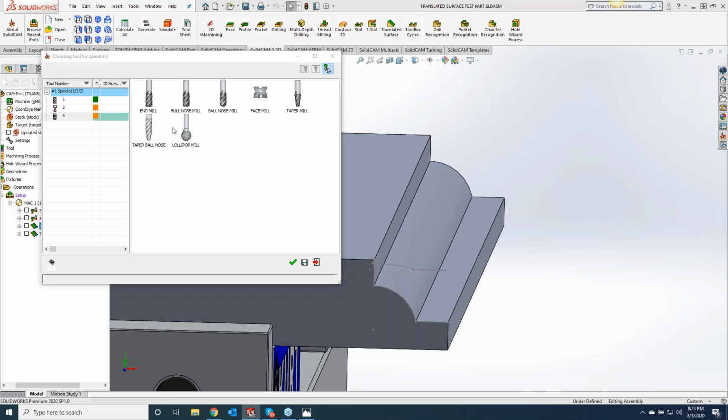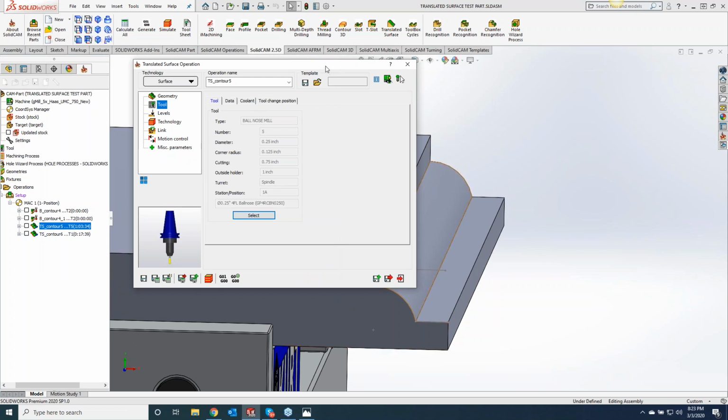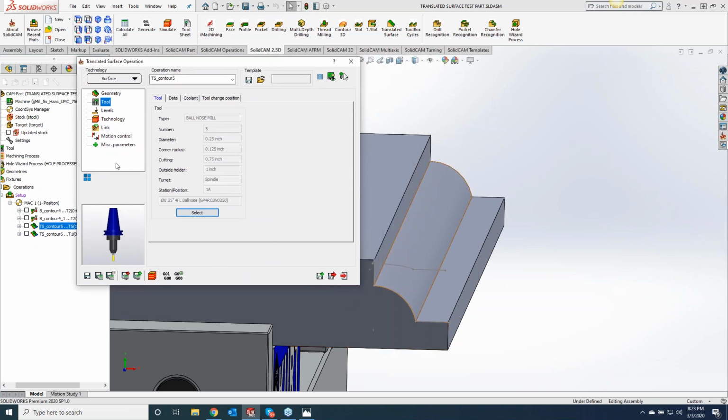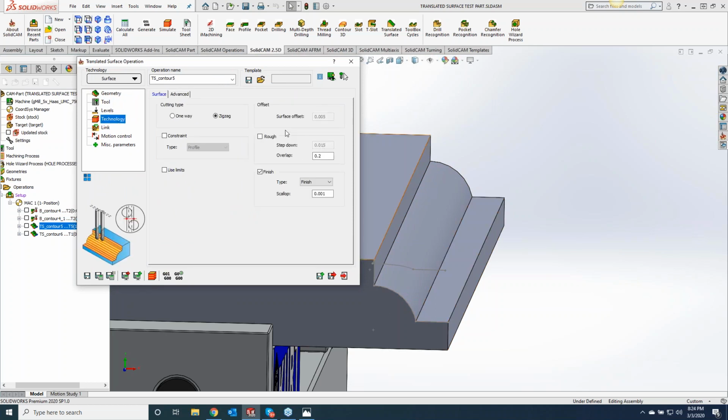And the roughing strategies work quite well in here. I was actually quite surprised when I started digging into this last week how well the strategies are in here for you. Like I said, you get a lot of control just by turning on this rough right here. When we turn on a rough, it's kind of like doing a profile operation. So we're doing these roughing strategies, leaving 5 thou on the wall to come back for that finish operation to clean up that 5 thou that was left over.